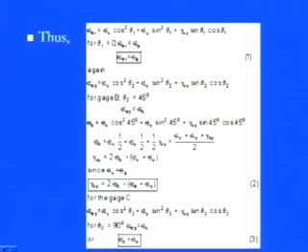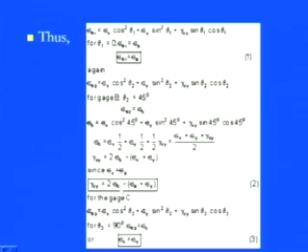So you see the meaning is that we have strain relations. If you want to get the shear strain part, gamma xy, you multiply by 2 times (2 epsilon b minus epsilon x plus epsilon y). That means if you know the normal strain component at the middle portion, at 45 degrees from this one, you can easily get the shear strain component from that. Or we can say that gamma xy is nothing but equal to twice of these terms.